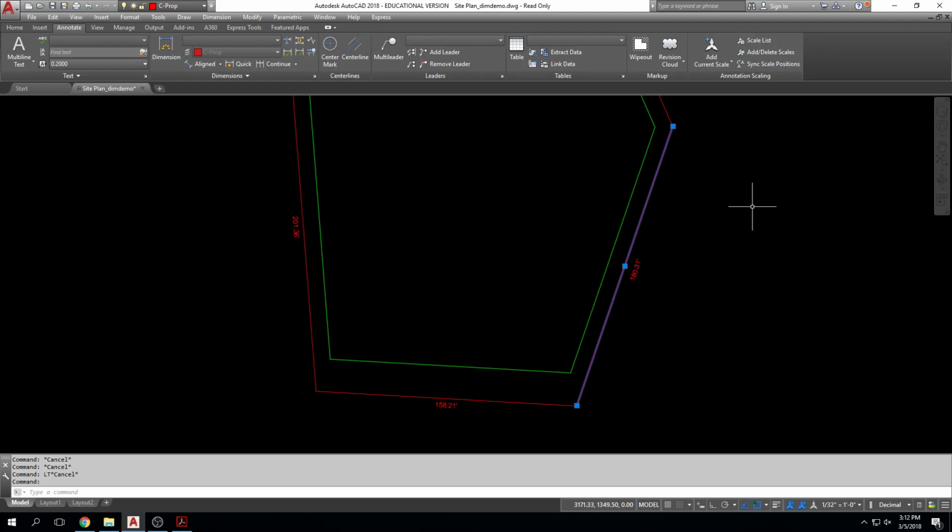So what could have happened is you actually did dimension it and it's not showing there. What's happening is your annotation scale is 1 to 1, which means you have a 3/32 inch tall piece of text next to your line. So if you go 1/16, okay, now dimension it. There you go. You may actually want to do an aligned dimension so that it doesn't go horizontal. It goes in alignment with the line.